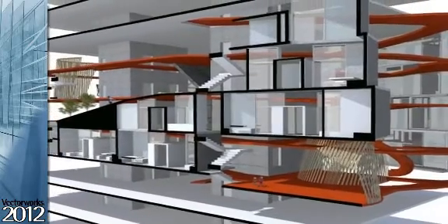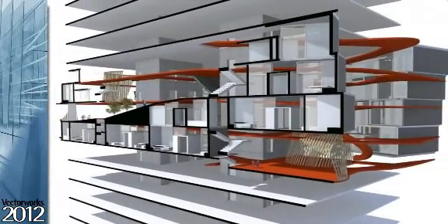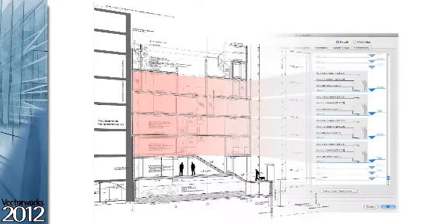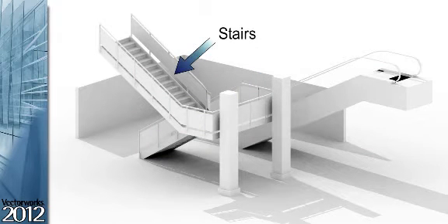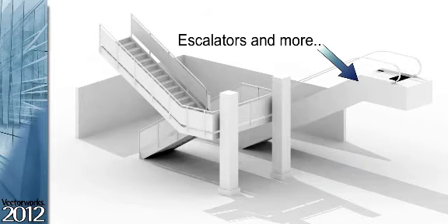Modeling multi-level buildings just got a great deal easier with the introduction of Vectorworks Stories. The concept of stories can be envisioned as either a container for or a grouping of layers, resulting in the ability to respond to changes even more quickly and accurately. Many of the common parametric objects you're familiar with are now story-aware.